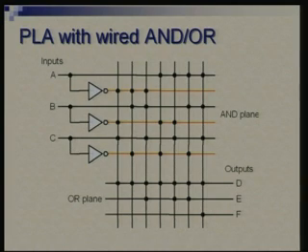So in actual practice, the AND gates are formed actually vertically, so they are distributed. I am not showing the exact circuit. At each cross point there will be a transistor which you will connect to the cross wire, or you will not connect. Okay. So I suppose we will leave those details to a course on digital hardware design, which you might do later, but just in overall functionality you understand this, that it is a programmable structure which can be automatically generated from the given specification.